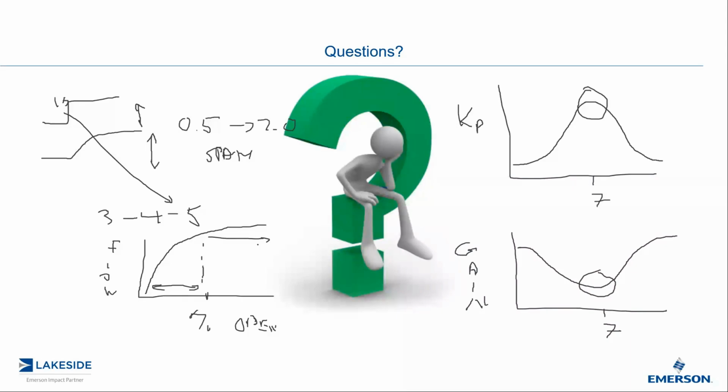I've actually implemented adaptive tuning in the form of a characterizer. This was done because it actually wasn't a butterfly valve. It was a globe valve on a boiler feed water, and the actual pump was wearing out, not the valve. So I had to implement a characterizer on the output of the feed water flow controller in order to linearize the flow characteristic and allow the PID controller to control better at the upper end.